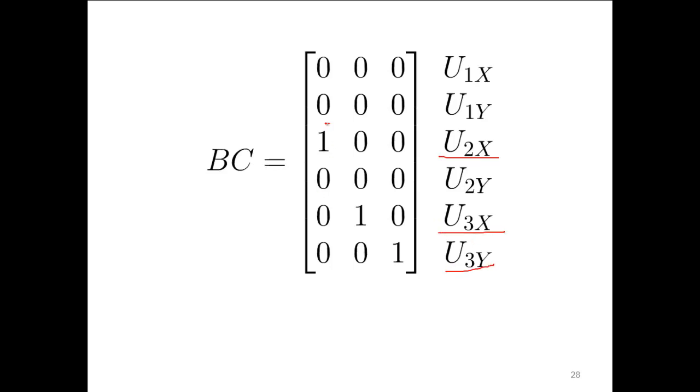So there's a 1 here, here, and here. So it's a 6 by 3, 6 because we have 6 different coordinates between our 3 nodes. And then it's a 3 because those are the only 3 displacements that are left to solve for. All right, so there's the u2x, displacement at node 3 in the x, and then displacement at node 3 in the y.